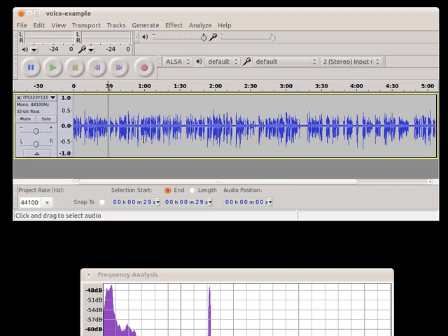That's the sampling rate. So the analog data is coming in, and it takes a sample at a rate of 44,100 times per second. It says here there's a sampling of 32 bits, but if I save it as a file, I can specify the number of levels to save it as. A common number of levels is 16-bit encoding.